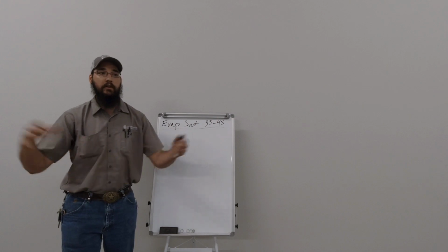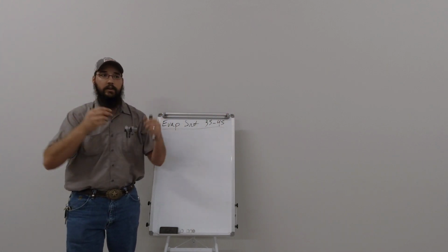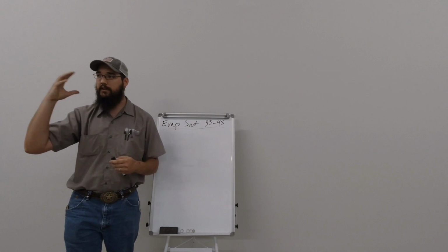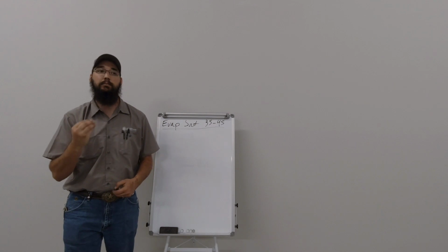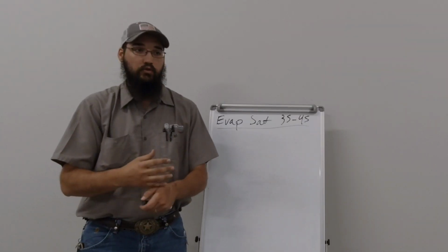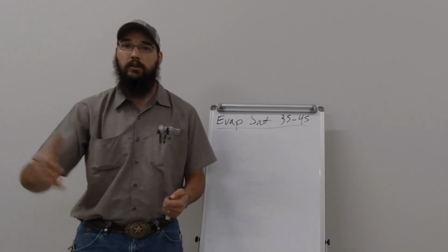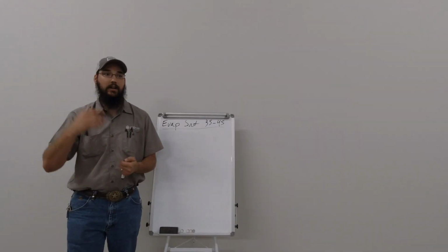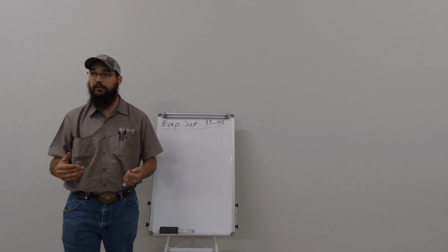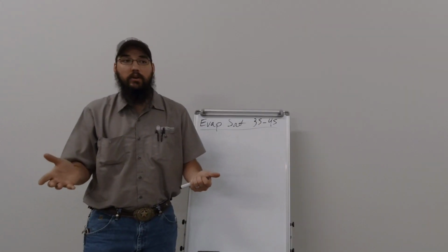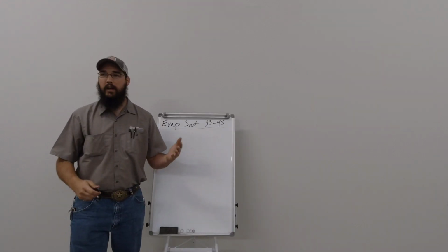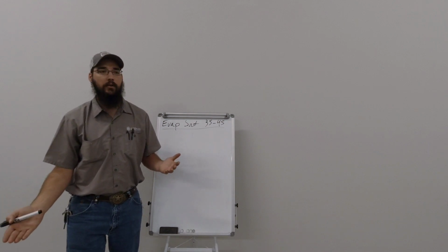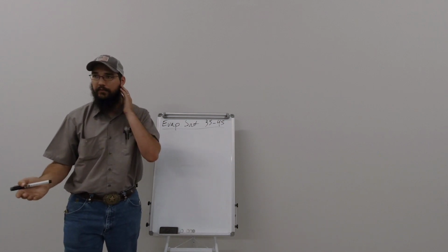Well, to take it a step further, it only makes sense to make that condenser so big, not just from an engineering perspective, but also from a cost perspective. And we see them get just stupid large for condensers. I mean, heck, they're as tall as Curtis sometimes. He could stand up inside some of them. 5-ton condensers. But the point is, that's where they're taking it. That coil can only go logically so big. Well, then it also made sense, okay, if we can only bring the condenser so far down, because there is a limit to that, we can only go down so far, we also need to increase the suction.